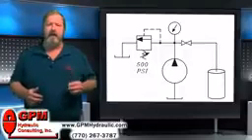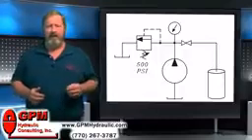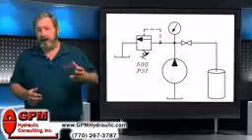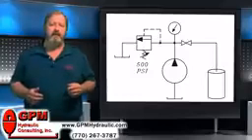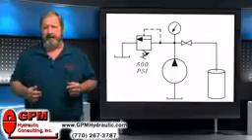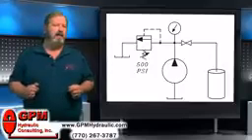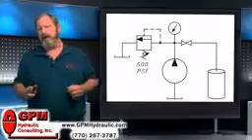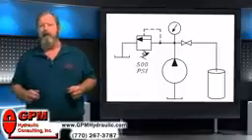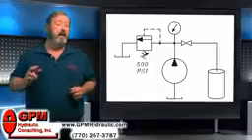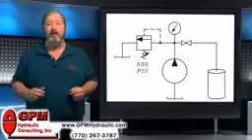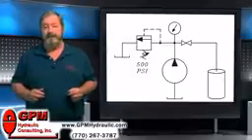It delivers a rate of flow. That flow meets with and hopefully overcomes a resistance. And the result of this is pressure. So what you're reading on a gauge is not how much pressure the pump is putting out. What you're reading is the amount of resistance currently being overcome in the machine.